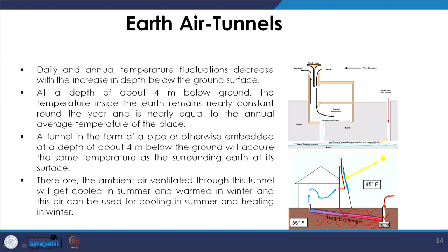So, when we pass the air through this tunnel, the tunnel and the mass around the tunnel absorbs the heat, or provides it with added heat in case of winters, and then this air is taken inside the habitable space and the space gets cooled, and when it gets hot it is exhausted out. It is not absolutely passive because we require fans, we require pumps to bring that air from outdoor into the earth air tunnel and take it into the room.